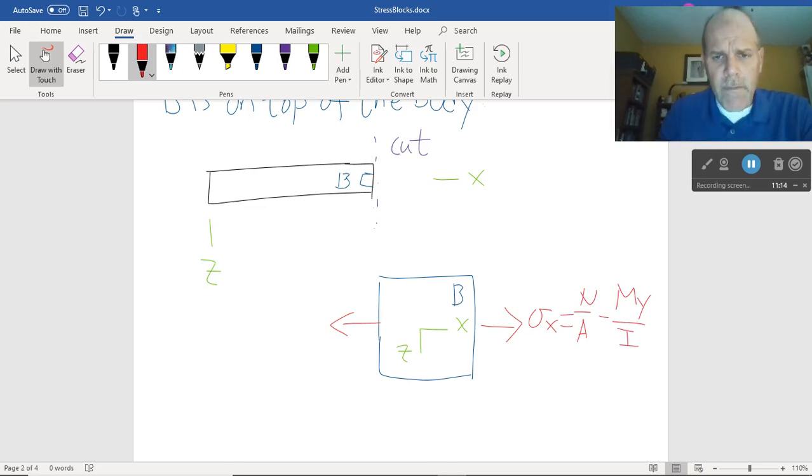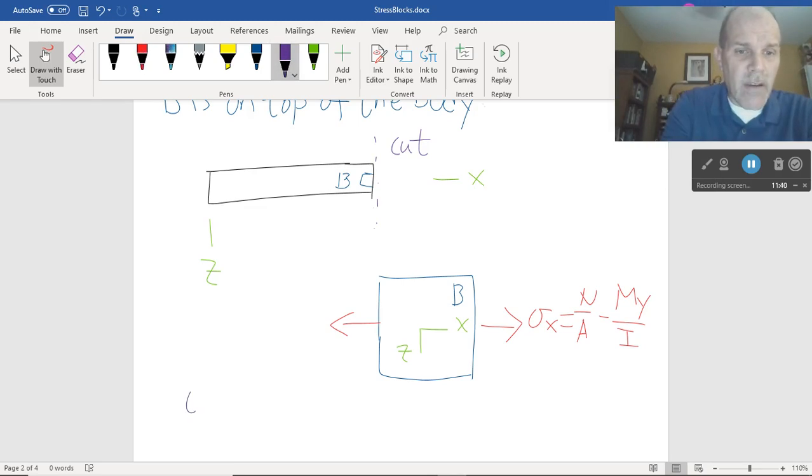That shear stress, though, right? That shear force was in the y direction. The shear force is coming out of the page at me. Shear out of page. Shear out of page. Doesn't sound like shear to me. And that's because, again, it's a y-directed force on an x-directed plane, right? So what this is telling us is that the force V does not cause a stress here.